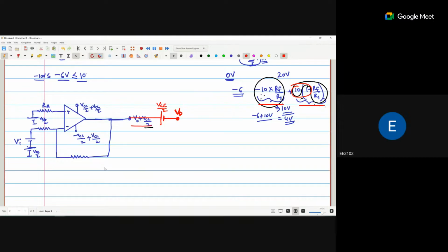If you use a mobile phone, your battery is at 100%, fine. If it is 0, you connect it to the AC. So that means anyhow you require a 220 volt supply. Now 220 volt to 5 volt or 9 volt, whichever operational amplifier you are using, to convert to plus 5 volt and minus 5 volt, you require two different circuits for that. So your complexity increases, as well as you have three different voltage levels: plus 5, ground and minus 5. If the circuit is small, okay, fine.